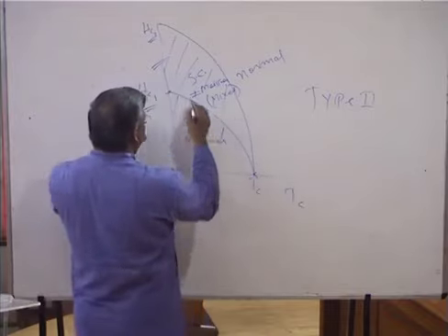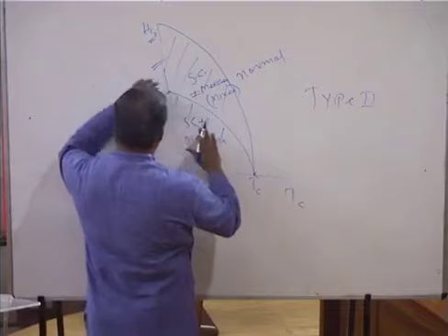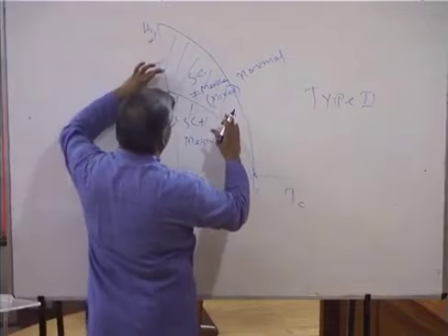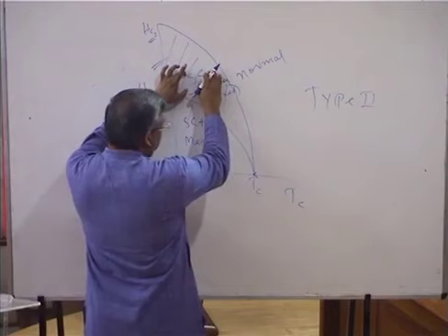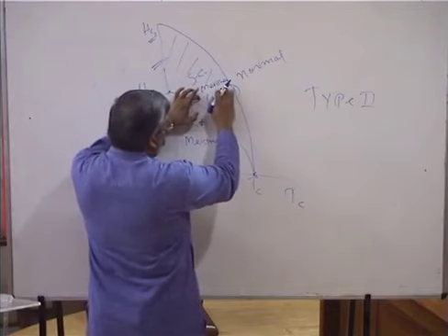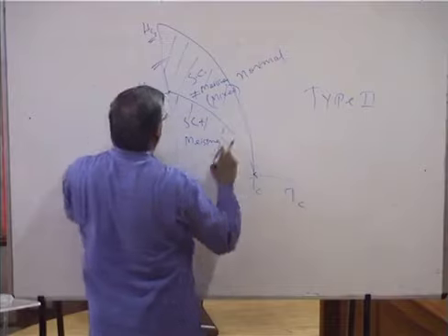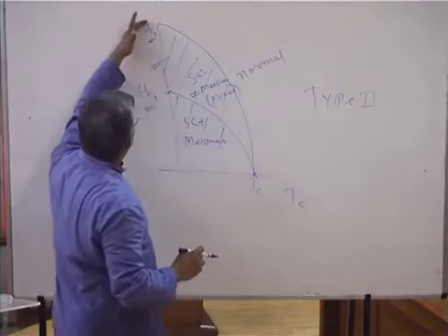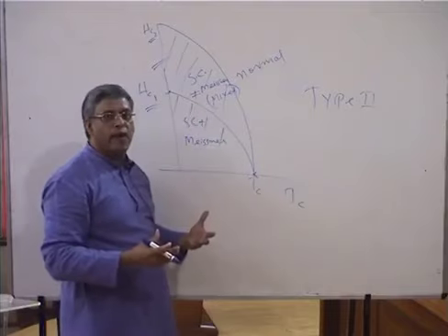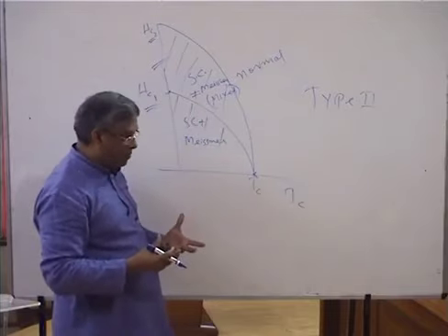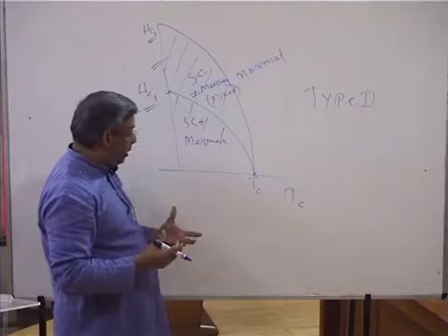This is the superconducting and Meissner region, below HC1. Between HC1 and HC2, you have a mixed region where the material is superconducting, absolutely interesting, but it's not perfectly diamagnetic. It does not matter, because what we look for is a high value for HC2 in order to allow a large amount of current to be carried by a wire made of superconducting material.